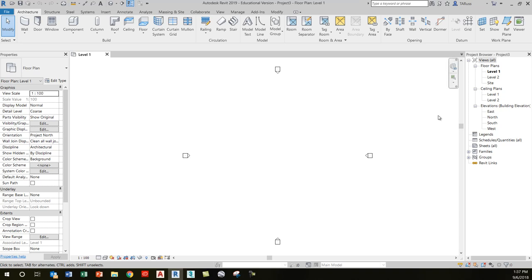All right, so I'll elaborate on that a little bit more. This is one of the most important elements of the Revit interface, something that you wouldn't be accustomed to seeing in another program. The project browser, as you can assume already, is where we stash all of our views. So as we work on the 3D model and we need to go to different views to see what those drawings will look like, we use the project browser. It's one of those things that just stays open all the time. Other little windows will be context sensitive, come and go, but the project browser and the properties windows are two that you want to have open all the time.